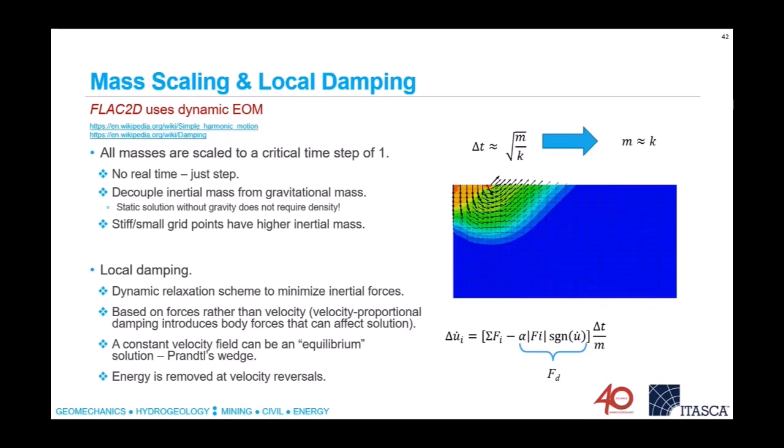We can stop solving, like we don't need to iterate forever to see how material deforms. You basically see the material deforms and continuously deforms. But we still need to stop this iteration in time somehow. So in that case, we actually use this velocity proportional damping of a classical dynamic system.